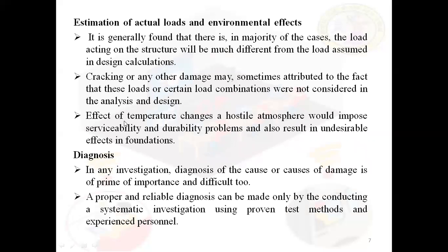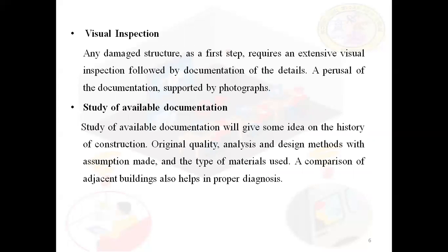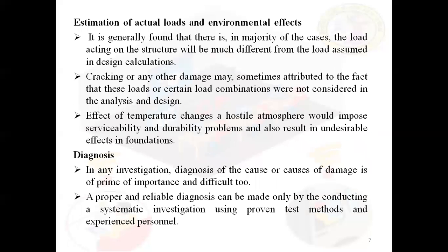Next, we have an estimation of actual loads and environmental effects. This is also one of the very important steps, that is after collecting the documentation. We have to find the actual loads and what the environmental effects are on that. So we have to study with respect to what the actual loads are, what loads were assumed, but what is the actual load which is applied at the site.